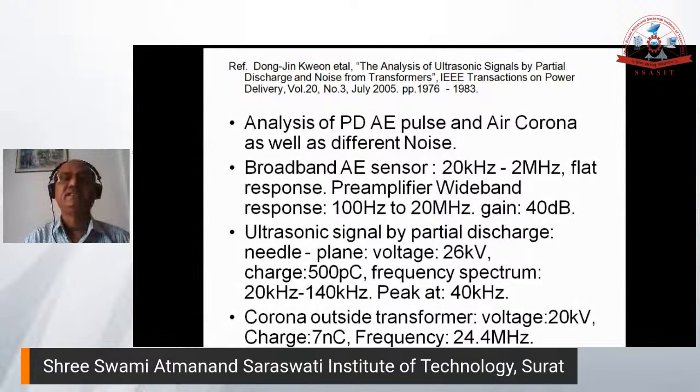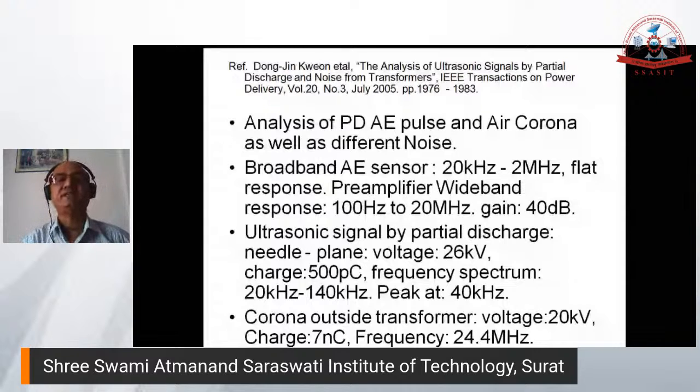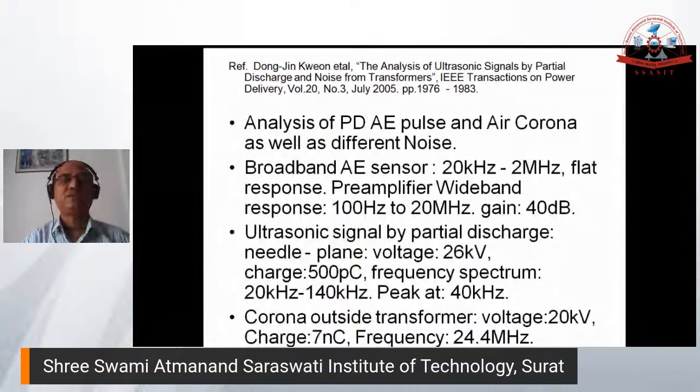They all create partial discharge or corona discharge, which also creates acoustic pulses. If those pulses are misunderstood as coming from inside, what is going to happen? So this frequency analysis can help you understand the different frequency ranges of the different types of discharges.